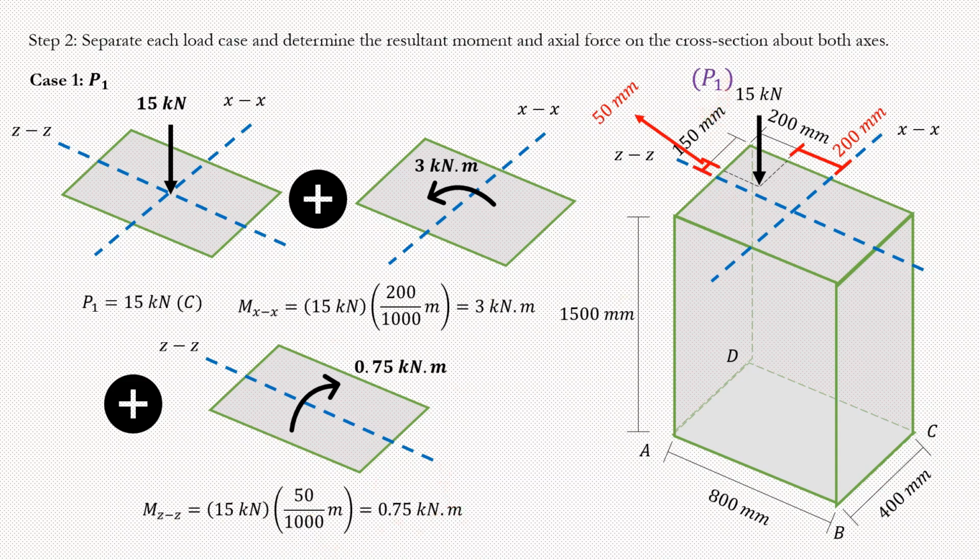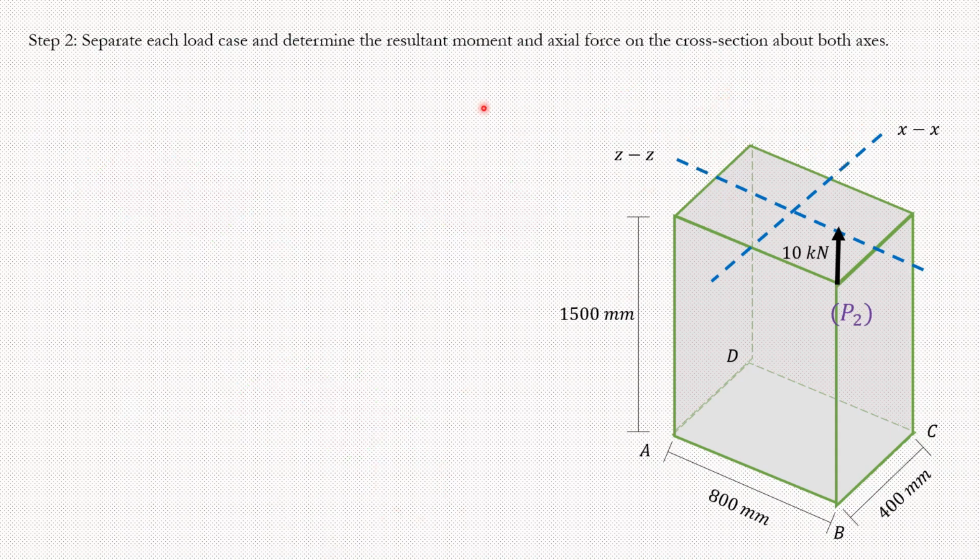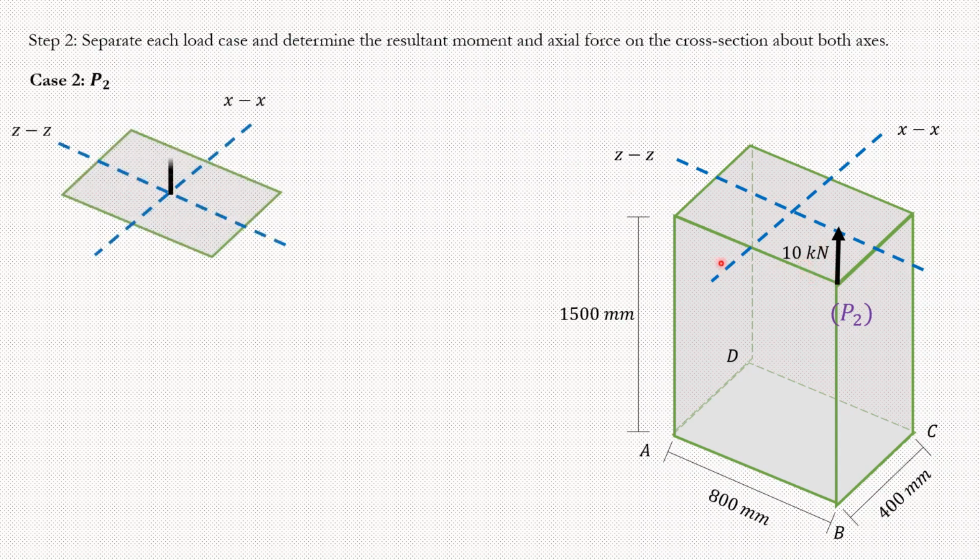After this, we're going to repeat the process that we did for other types of loads. Let's say you have a load that is pulling on the cross section. Here I have a 10 kilonewton load that's pulling. Again, it's the same idea. We make the force concentric initially, but we take into account its moment effect. So I'm going to bring the load to the middle. It's going to be concentric, simple as that. It's going to be 10 kilonewton.